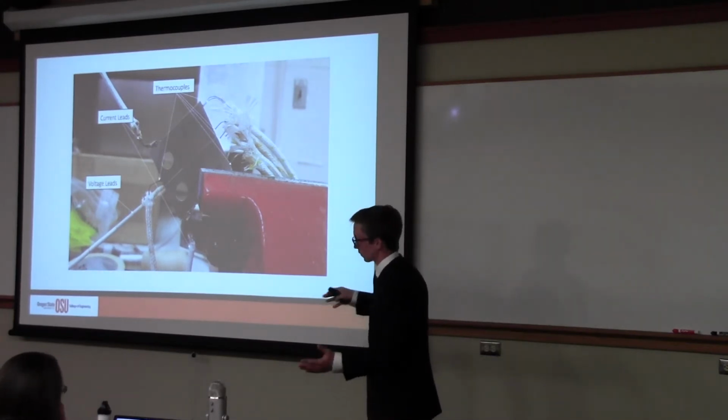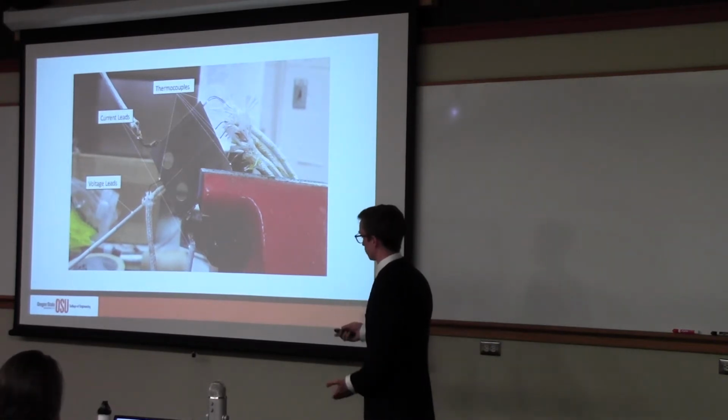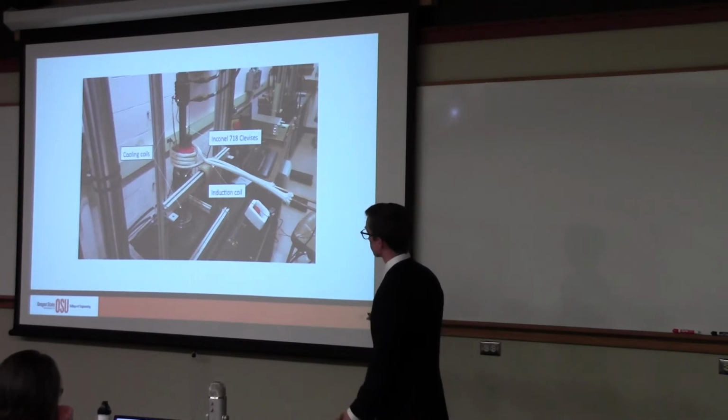And you get the crack length out of this whole thing from the voltage, and then you take the derivative of that, you get the crack growth rate, which is ultimately what we're after. This is what the setup looks like.